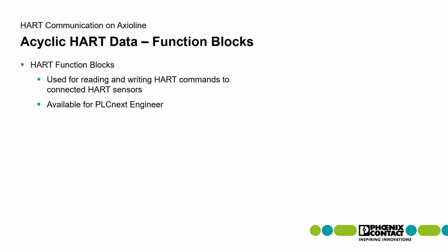Fair warning, this is a bit complex, so this is not going to be for every user. But if you have HART devices connected to AXL I/O, whether it be on AXL F, AXL P, whether it's next to a bus coupler in PROFINET or on a PLCnext 2152, you can utilize HART function blocks in PLCnext Engineer to actually read and write to that HART sensor. So let's get into it.